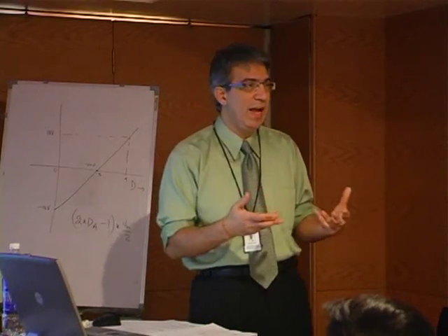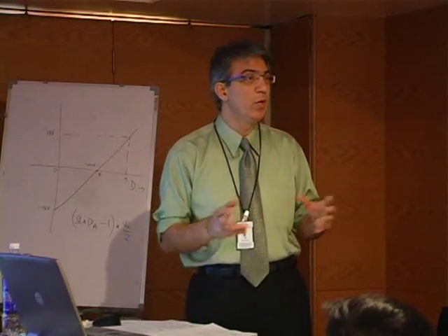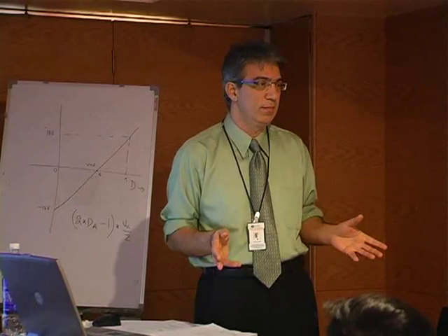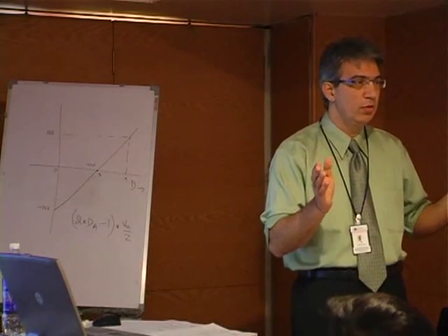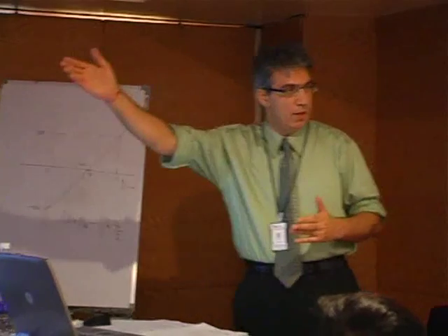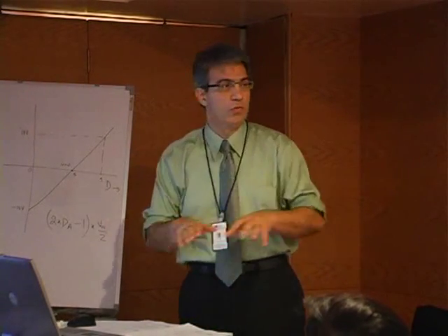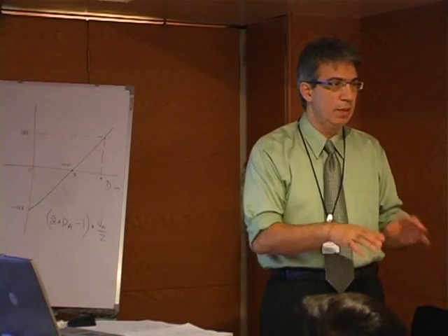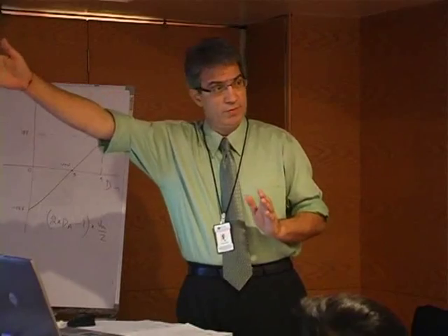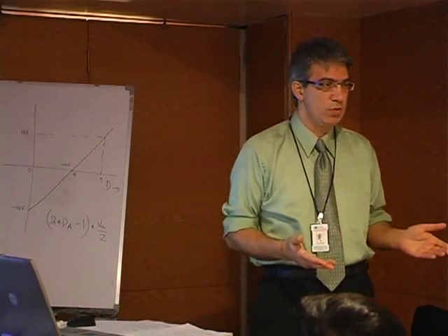And if I can have MF where I have a switching frequency of 20 kilohertz, you really don't have to worry about any part of it. At that point of time, you are above all the theory. So if your MF is large enough, then these rules are less applicable. And plus the harmonics are so far off that they will not really matter in the actual performance of the motor.